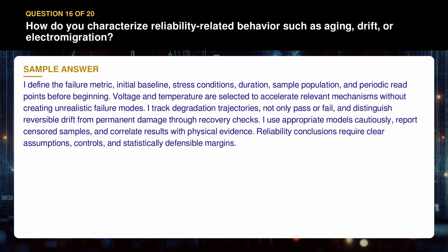I track degradation trajectories, not only pass or fail, and distinguish reversible drift from permanent damage through recovery checks. I use appropriate models cautiously, report censored samples, and correlate results with physical evidence. Reliability conclusions require clear assumptions, controls, and statistically defensible margins.